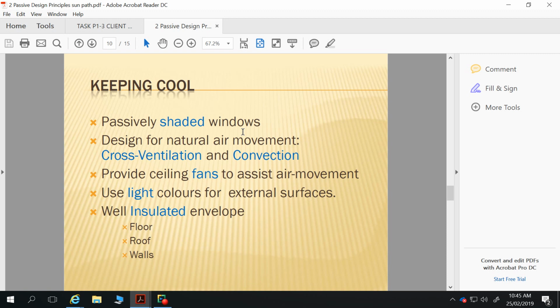But typically when it comes to insulation, it's more a question of how much money you want to spend and where that added benefit is going to come from. And you can't always just insulate yourself out of a problem. Sometimes it's better to have better consideration of siting and orientation and crossflow ventilation and things like that, rather than simply relying on insulation and also on air conditioning.